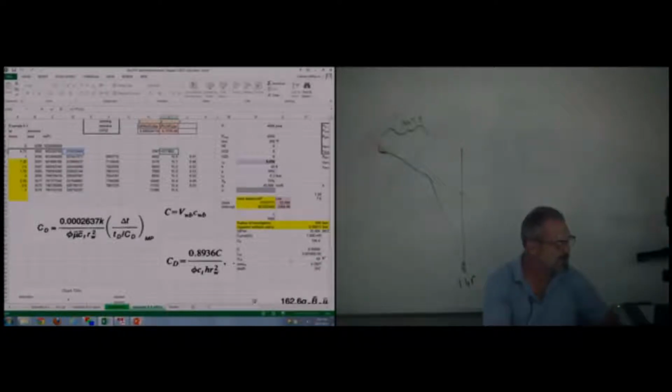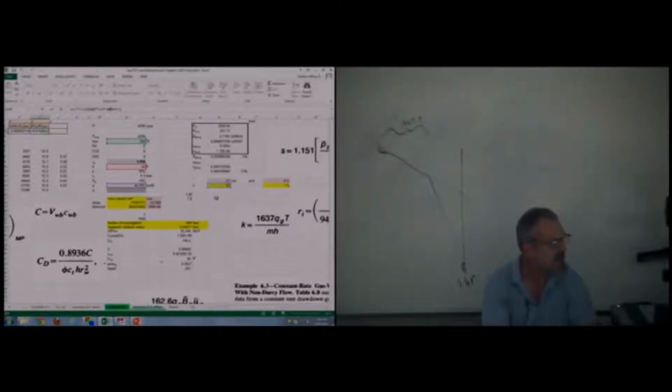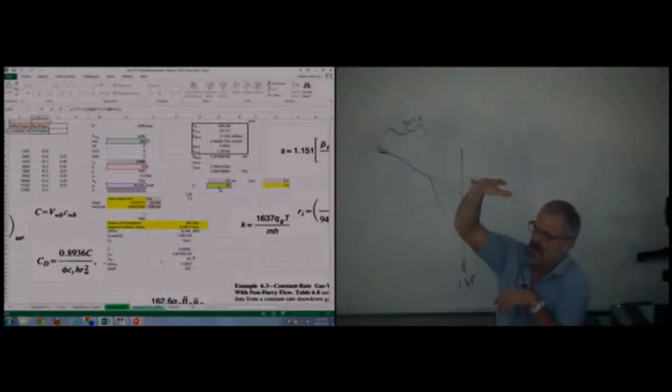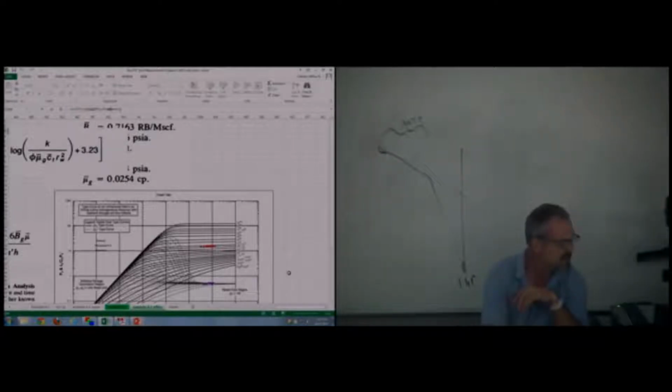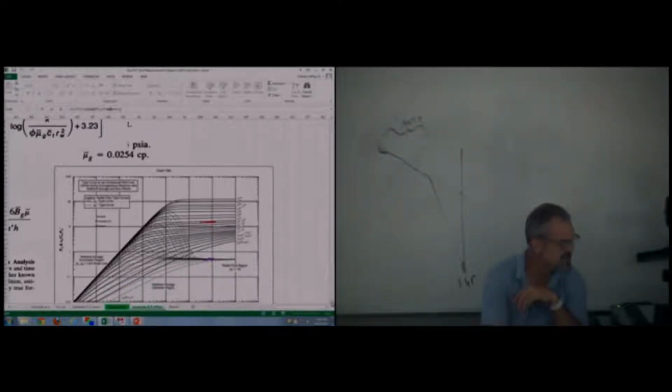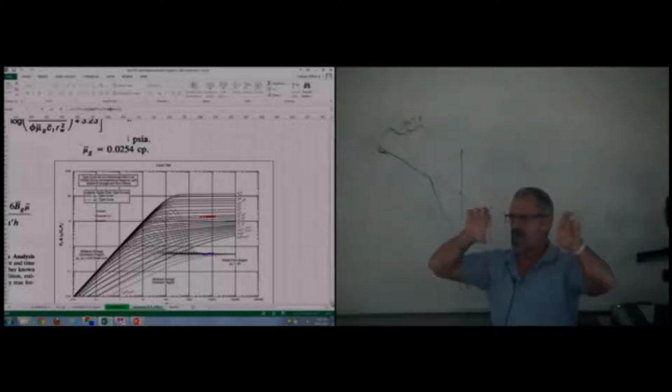And that coefficient is only a function of things that I already know: reservoir temperature, height, flow rate, permeability. Okay? So that's my height adjuster. It takes all my data and my derivative data and fixes it, so that when I'm on my type curve, I only have one handle left. I can slide that to the right and to the left.